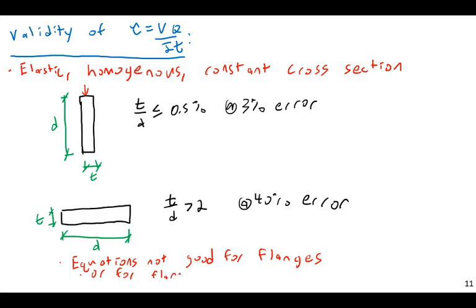Those are stress concentrations. In other words, anywhere you get a discontinuity, there are obviously some issues. The equations really won't be valid, since real materials don't exhibit harsh vertical discontinuities like that. If you're going to really do something like that, there are equations in, say, steel design that you can use to design flanges for shear, but they're a bit more involved than our simple equation here. So, stress concentration.